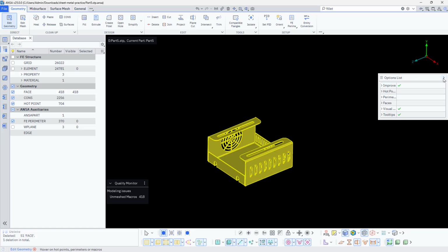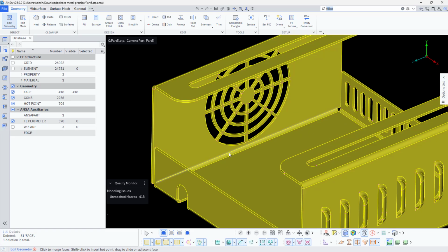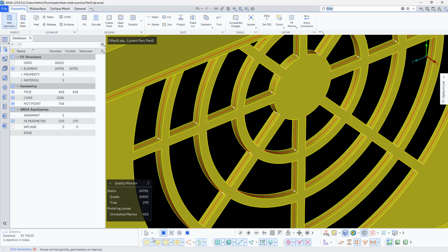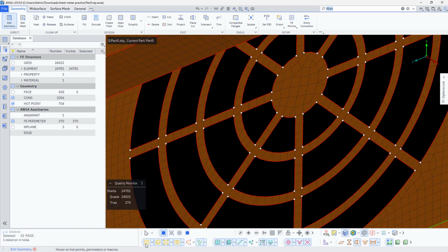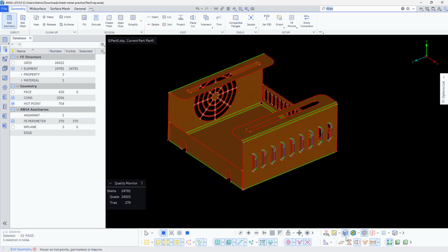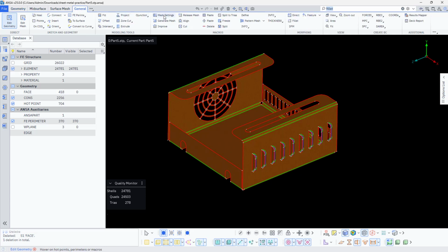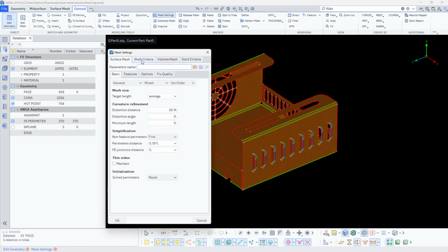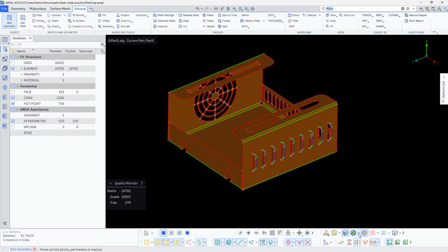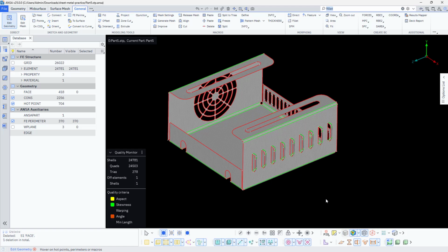Yeah, so now if you compare this with the mesh, it will show the exact region which has been captured properly, right? Well, now let us switch to the quality criteria. Before that, I would like to set the mesh criteria in the shell: aspect ratio, skewness, min and max angles with respect to trias and quads. Now here in the quality, just set the criteria.